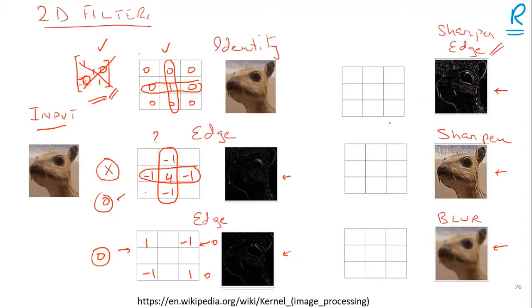How would you make an image sharper? So you take this particular edge detector, you want to make it sharper. What can you simply do? Multiply it by 2, so you could make it 8 and minus 2, minus 2, minus 2, minus 2. Okay, and that is in fact this particular image. No, actually it's not like this. This actual image is based on the following values. -1, -1, -1, -1, and a -1. So you can see the total is coming out to be 3, 4, 5, 6, 7, 8, and -8 plus 8. So the total is coming out to be 0. Okay.